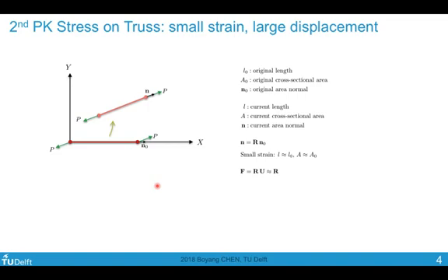So now, since we've mentioned that the length doesn't change much, our deformation gradient after polar decomposition remains only the rotation R. And the determinant is approximately 1 because we are not changing much the volume. And then if we calculate our first Piola-Kirchhoff stress, we have the determinant of F roughly equal to 1, and the F inverse transpose would be roughly equal to the rotation R. And then we are left with tau, which is our Cauchy stress tensor, multiplied with R, our rotation matrix. Then we calculate the second Piola-Kirchhoff stress, which equals F inverse times P.